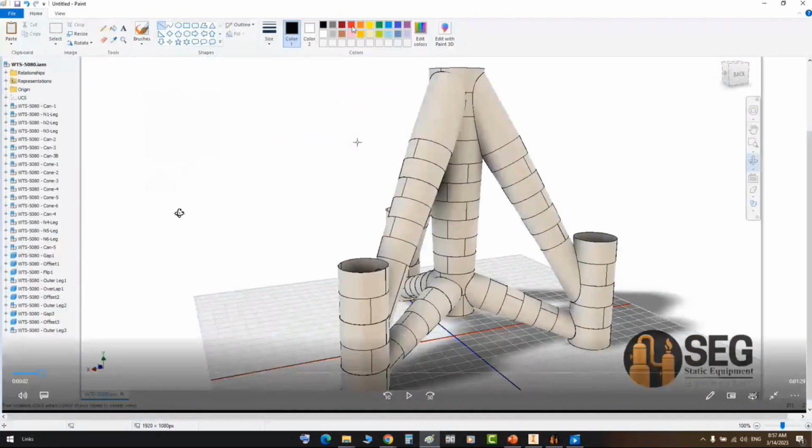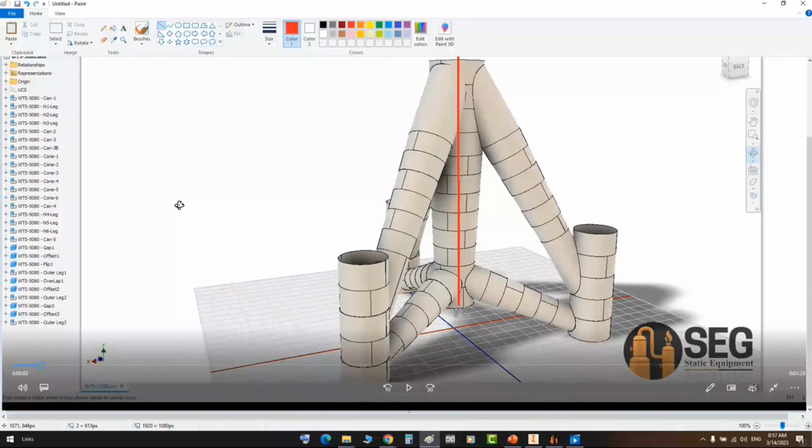After that, you can offset the center line from here to there, so you can make an offset. After that, start your other arrangement, and when you come back to this point, you can move from here to there and start your assembly in that direction. After that, you can move from here to the third one and start your assembly. By using this concept, which is offset, gap, shift and overlap, you can make an arrangement like that.